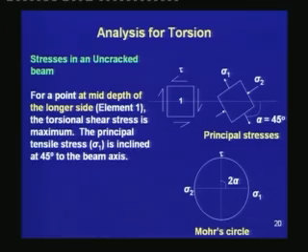It is easy to understand the behavior first for an uncracked beam which is considered to be homogeneous. The presence of steel in an RC member can be neglected before the cracking of concrete because the stress carried by the steel bars is very small.